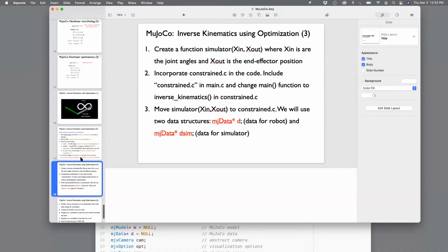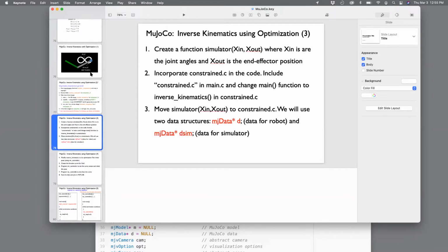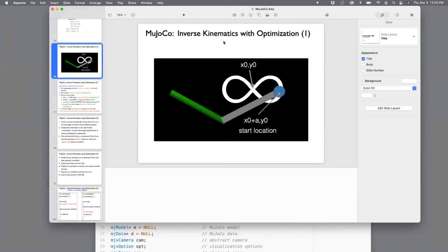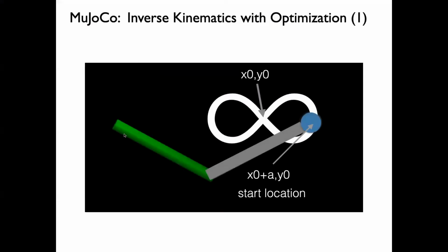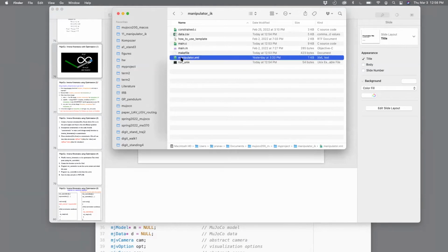First thing is, I don't think I wrote down the optimization problem, but the optimization problem in this case is simply, given the joint angles, let's say q1 and q2 for the two links, I need to be able to produce the position of the end effector. What I've done in this case is I've created a site, which is the tip position, and that basically gives me the position of the tip. This is a change I've done in my manipulator, the double pendulum class.